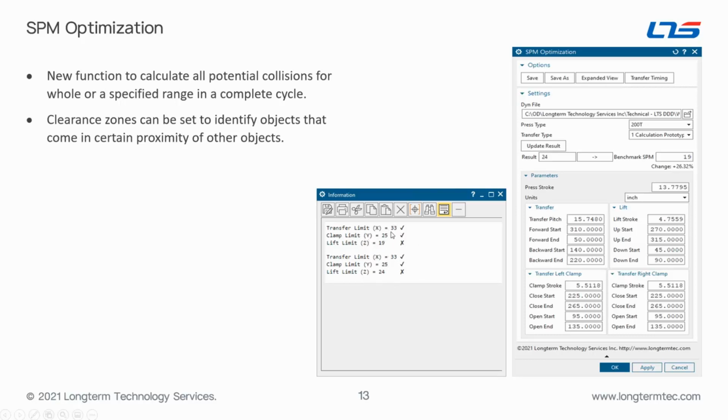As you can see here, in this example I started with 19. That was my original, and Z was the limiting direction. So if I optimize my Z parameter, I could get a better result. That's what I verified here. The limiting factor then was still in Z, but it was much higher than the previous one. Now, how would you achieve that in general? You would be optimizing, maybe adding overlaps if they are not causing any collisions, right? You would create those overlaps by modifying the lift entities. So that's what you would be getting, right?